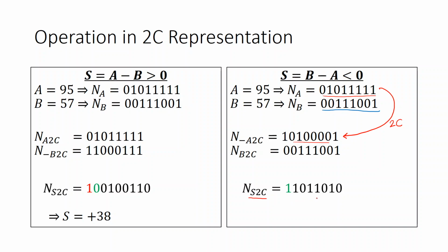You have not exceeded the limit of 8 bits. That means the MSB now gives you the sign of the quantity represented by this number, and the sign is minus, negative, which is what we should have obtained. However, how to find out the positive quantity?